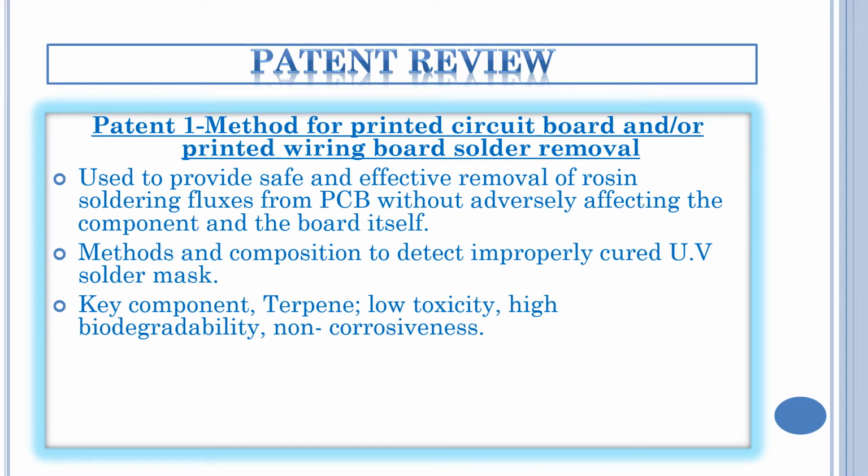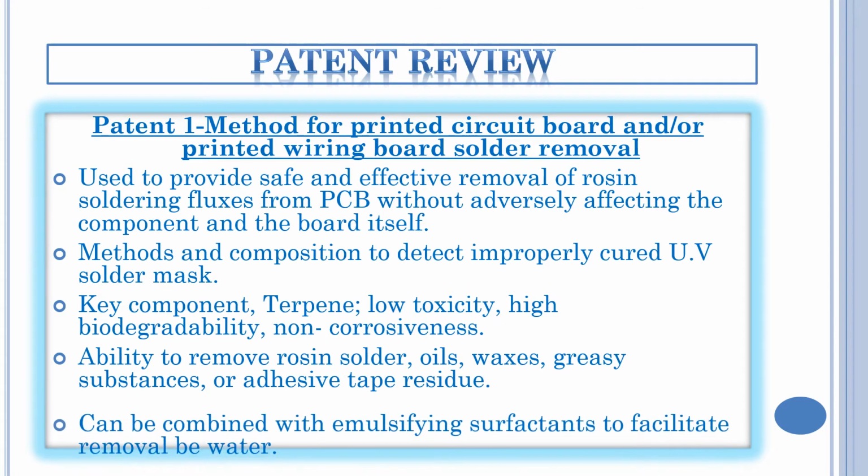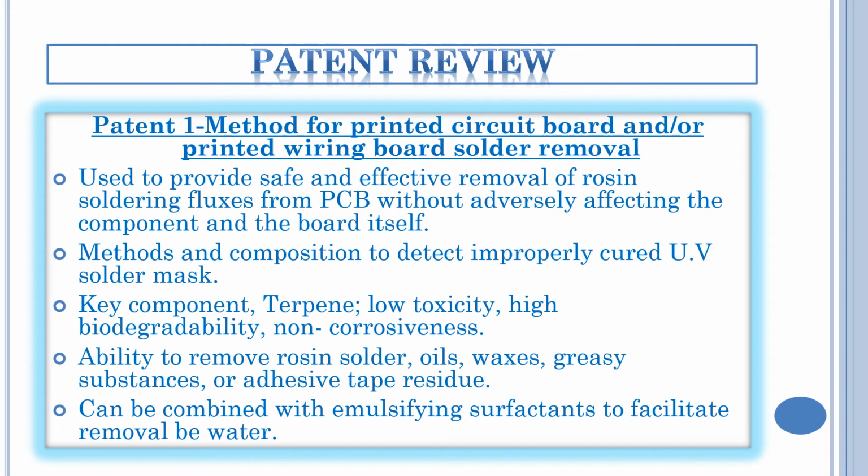The key component of the composition is terpene, which is characterized by its low toxicity, high biodegradability, and non-corrosiveness. It has the ability to remove rosin solder flux, oils, waxes, greases, and adhesive tape residues. When combined with emulsifiers, removal by water is possible.